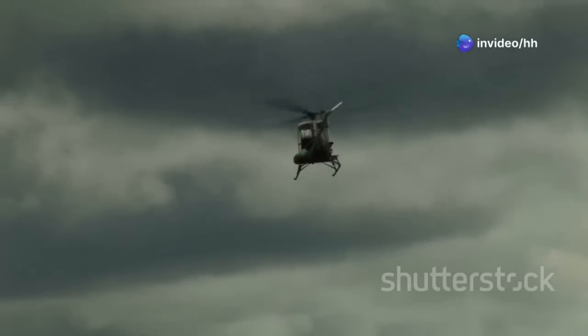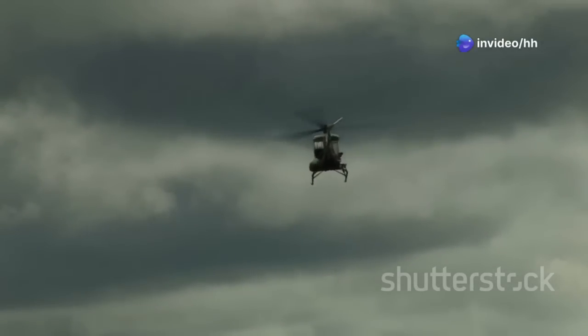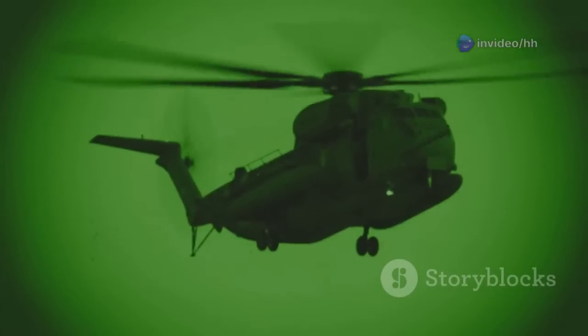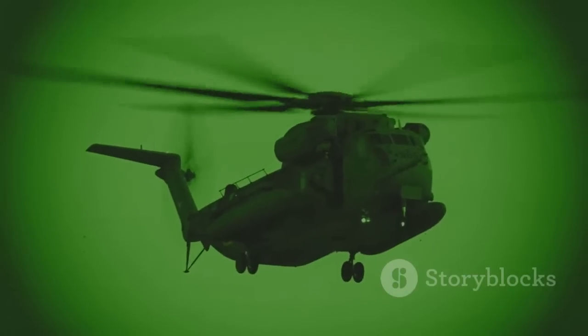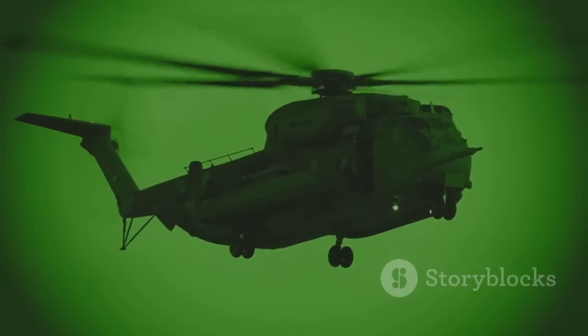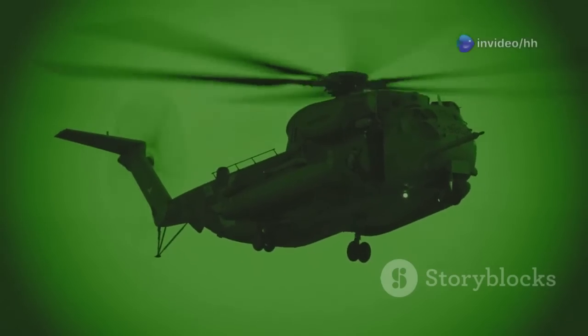Resultant relative wind. This is the direction the air flows over the airfoil. It's a combination of the air the helicopter is moving through and the air being moved by the spinning blades. Understanding this concept is vital for analyzing the aerodynamic forces acting on the blade. Induced flow. This is the downward flow of air created by the rotor blades as they spin and generate lift. Induced flow is a key factor in the overall efficiency and performance of the helicopter.